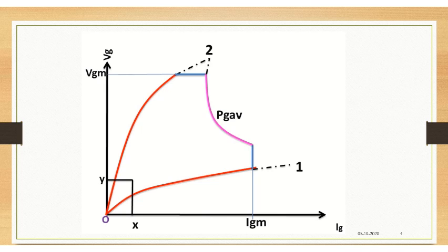If you recall the diode PN junction characteristics we learned in second semester, whenever you are using any device, you look for a safe operating point. How do you get the safe operating point from these characteristics? You will always draw a load line. Remember, you have to draw the load line. Wherever the load line crosses these characteristics, that point is the safest point where you can use your device.